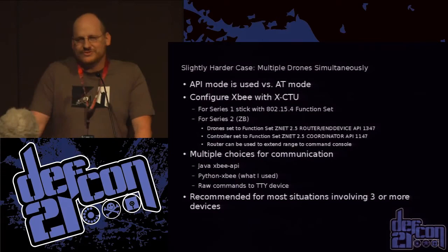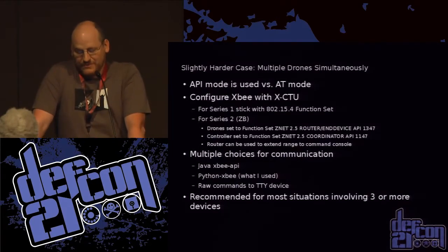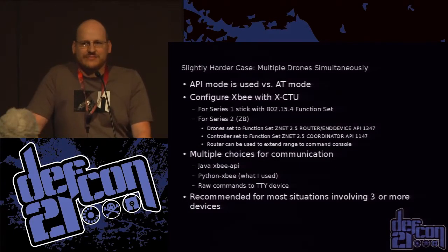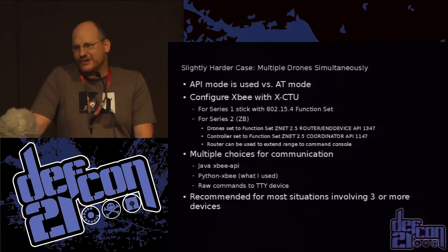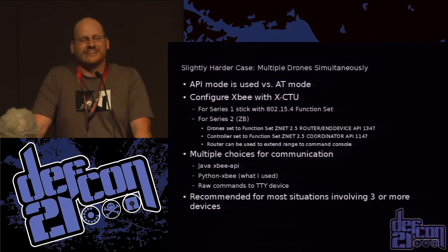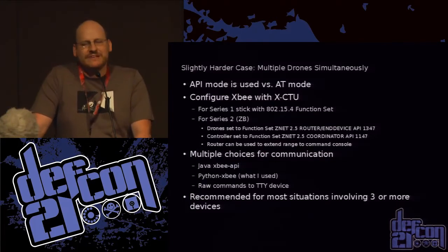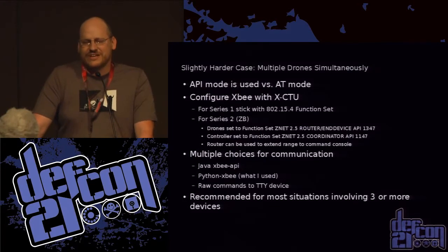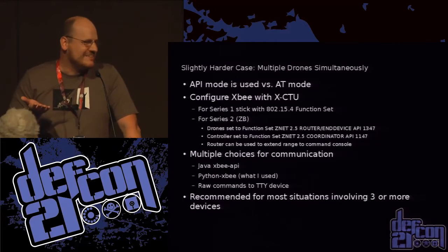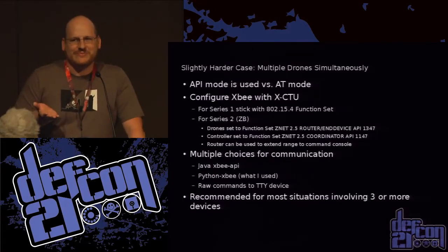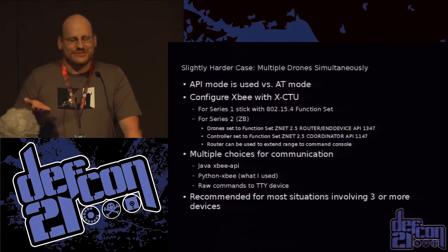I can also use an API mode, which is what I would personally recommend. The nice thing about API mode is that things are sent in packets, and it's a lot better for performance and error correction and all that good stuff. By the way, a little tip: if you didn't configure all your modems to use API mode and you're standing there going, it says it's receiving, why isn't it doing anything? And you're thinking, it's my Python scripting. It's probably just that you misconfigured the modem.